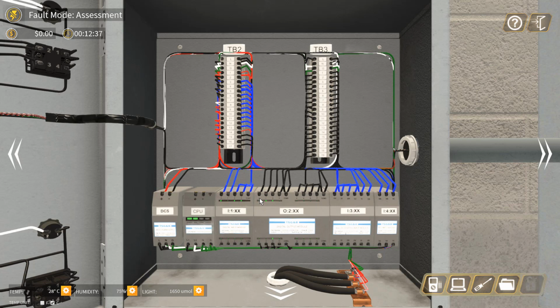it can be due to the PLC output switch having internally open circuit, or the PLC output channel 0 LED is burnt or open circuit, or even due to the PLC logic's virtual output coil not energizing, maybe because the software is corrupted, or maybe because the wrong programming was downloaded. Okay, but this is extremely rare. We can ignore it actually, so we don't know.